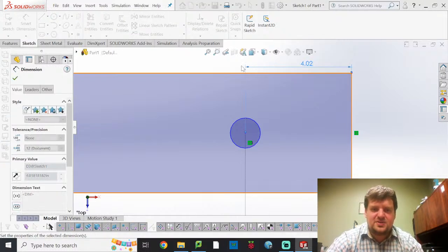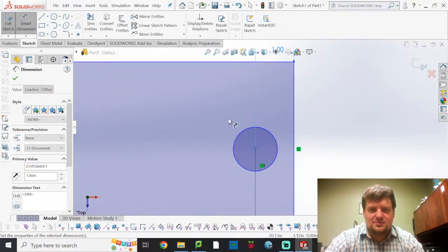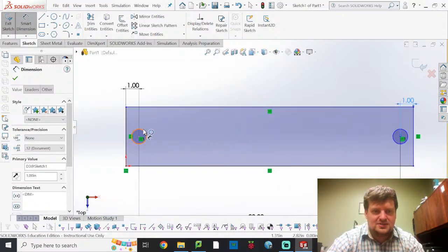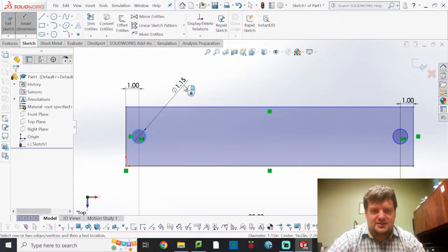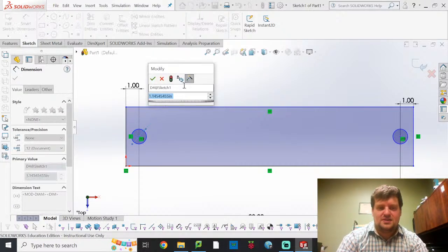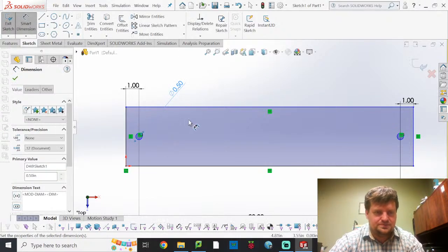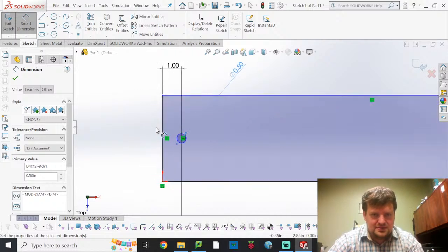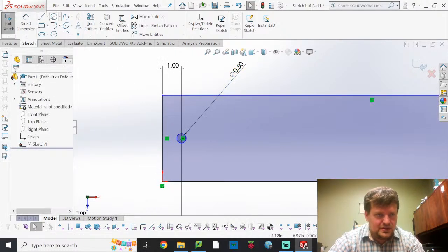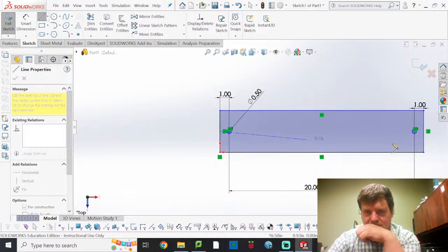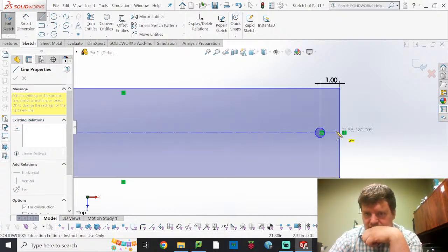And I'm setting this up in a very specific way because I'm basically going to take this file and just edit it multiple times. Make this be 1/2 inch. It doesn't have to be huge. I will draw a center line that goes from the center point here over to the center point here.